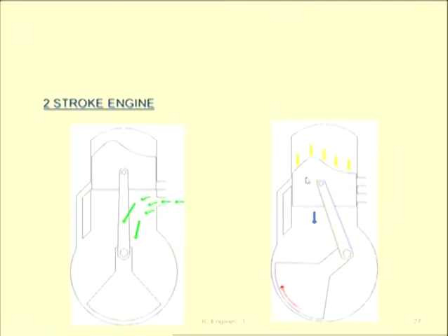Now at this position of the piston, my exhaust port is in closed condition, and the inlet port is also in closed condition. So whatever charge I have here, as the piston is moving downward, it is compressed. So the compression process will happen over here.